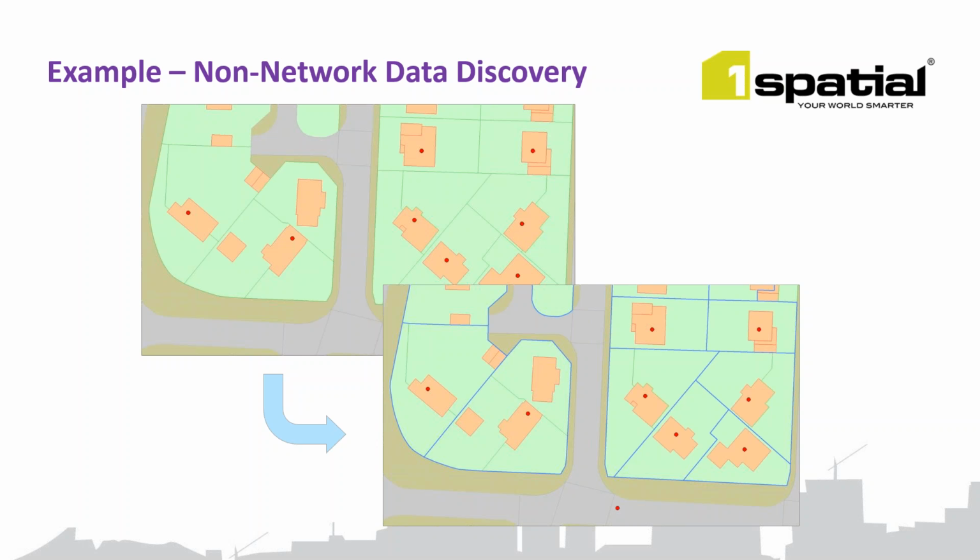Where are we feeding multi-occupancy buildings, which we need to be aware of, because there's obviously multiple people living in that property, which makes that property high risk. So if there is an incident in the area, we're going to have lots of customers affected inside one property. And if there's a dangerous event, we can react appropriately and speedily to cut the gas or take the operational step that's required depending on the property. So knowing where those non-network assets are is equally as important.